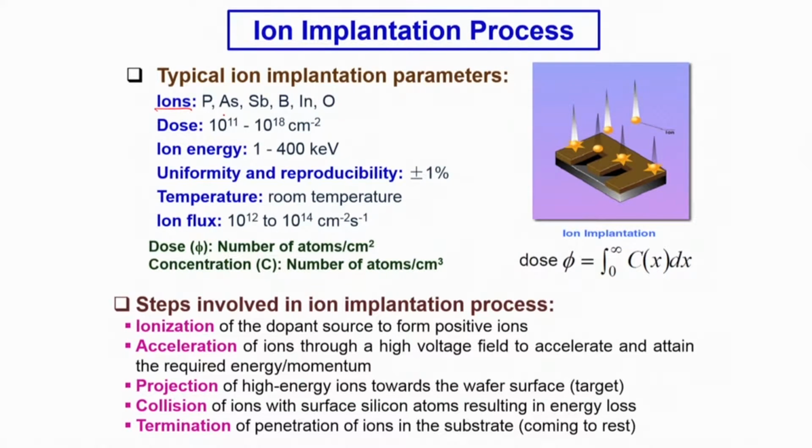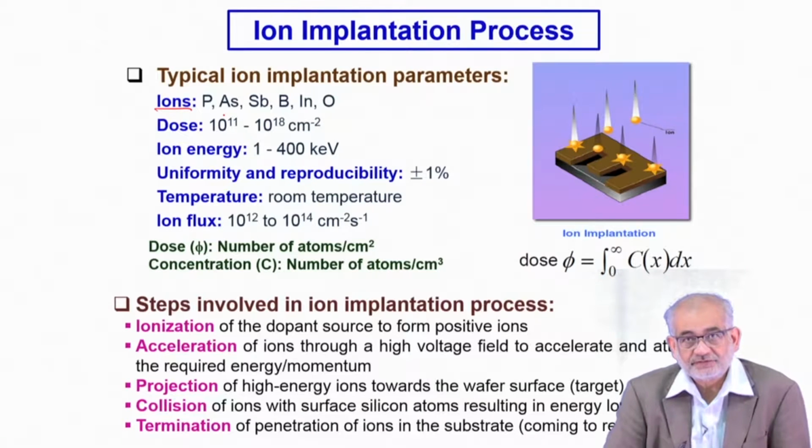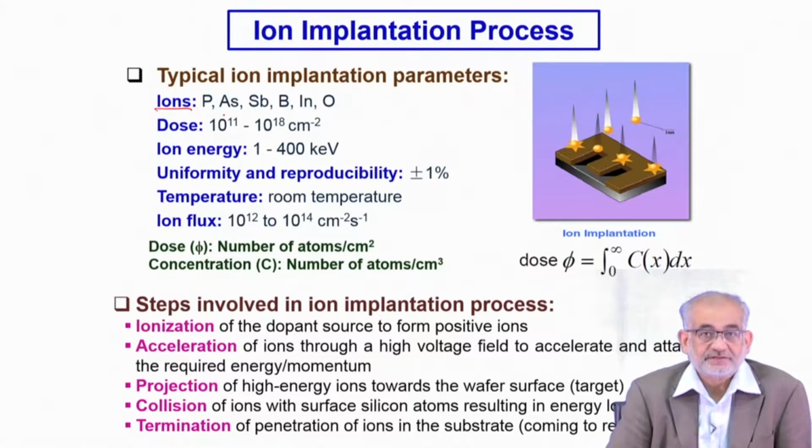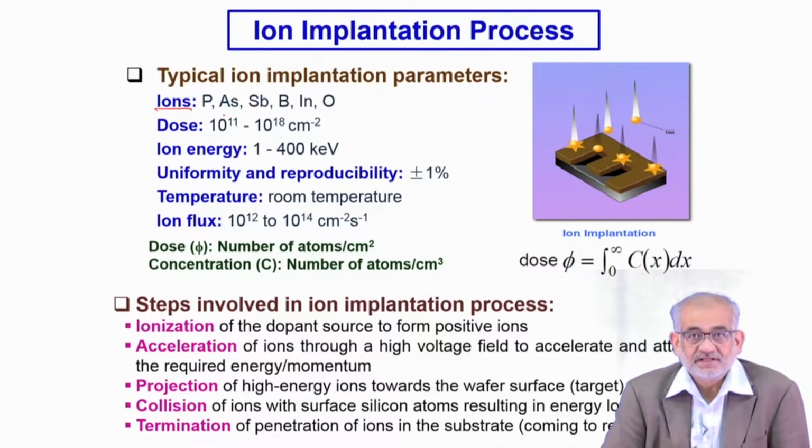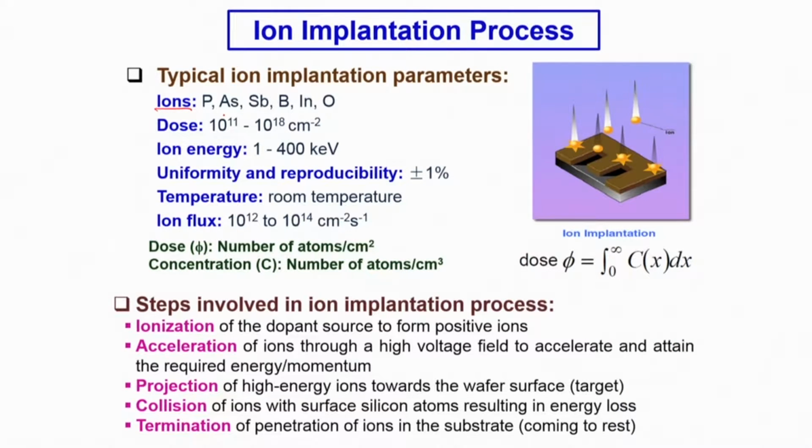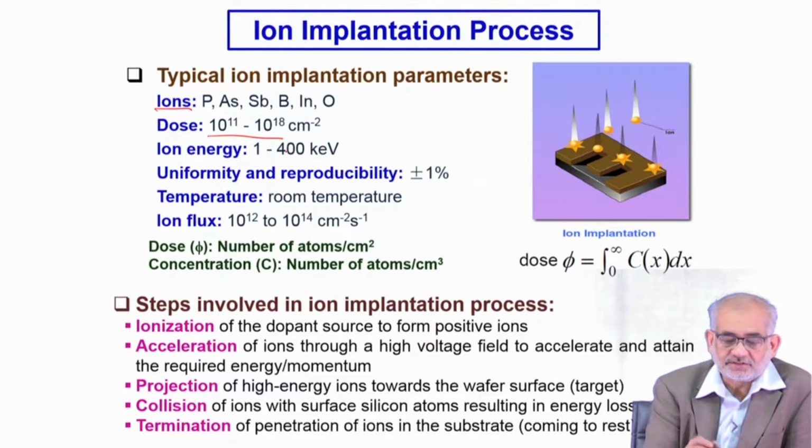species. By the by, the biggest and most widely applied application of ion implantation is in the semiconductor industry. That's purely because of the precision and accuracy with which you are able to carry out compositional change and hence change in electrical property. So we are talking about implantation dose, that is the concentration, typically about 10 raised to 11 to 10 raised to 18 species, number of species per centimeter square. So in a very small region, you can significantly alter the composition.